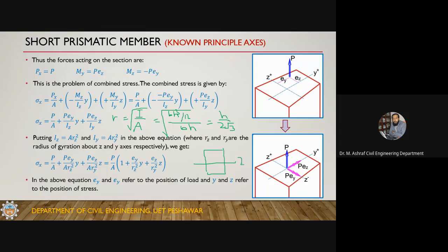Let's suppose this is the z-axis, and this is area A. If we locate the same area A as a strip at a distance of r, which is the radius of gyration, from the same z-axis, then both of them will result in the same moment of inertia.